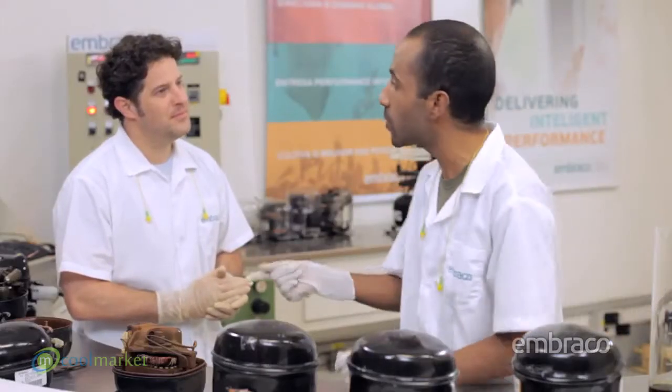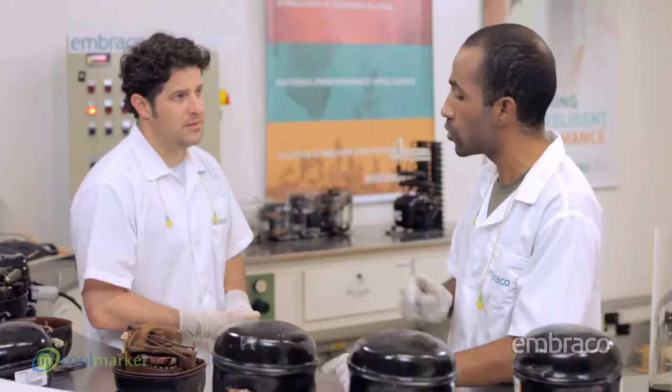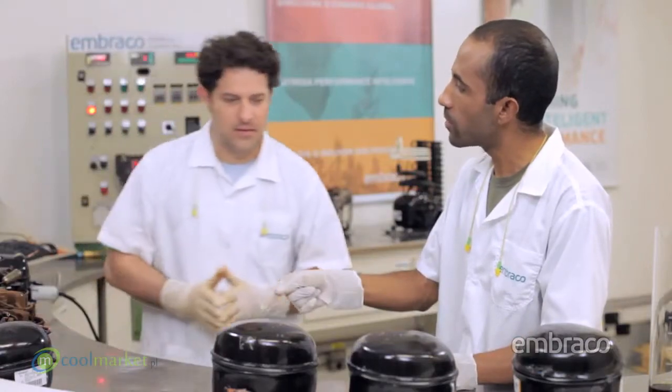This reminded me that the oil can degrade more quickly with contaminants in the circuit, such as moisture coming from microleaks, a vacuum process poorly performed, or poor quality refrigerant fluid, which act as catalysts. So we can say that this process impairs oil lubricating capacity and the compressor's performance? That's right. Speaking of chemical reactions, I've heard of people adding antifreeze to the compressor. Can this cause a problem?